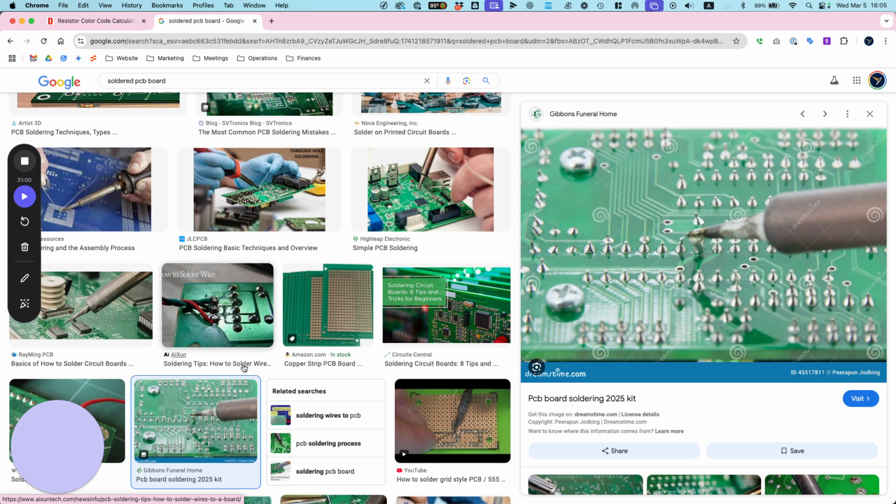Okay, you see, there's the wire. I don't like how there's a little gap here. You see right here? Anytime you have exposed wires, it's an opportunity for a short. So I'm actually going to just solder that some more while I push it on the back end.